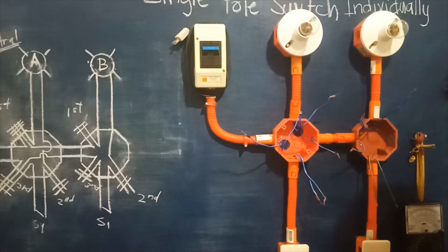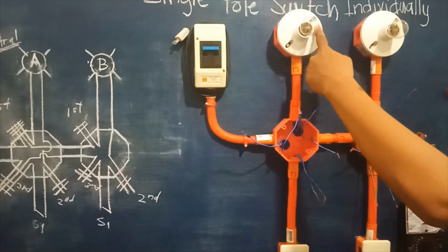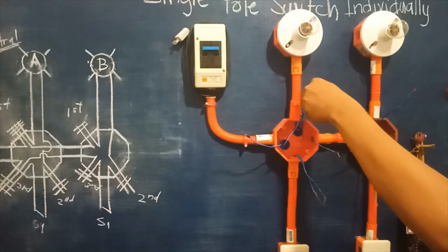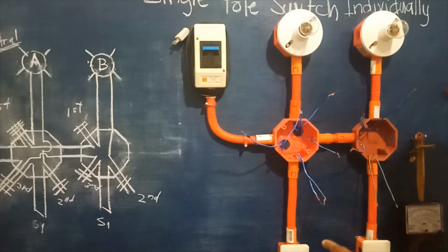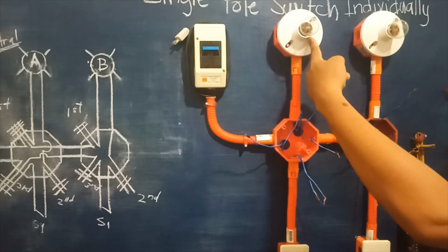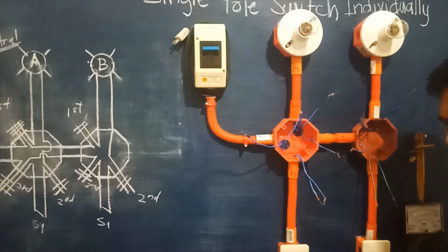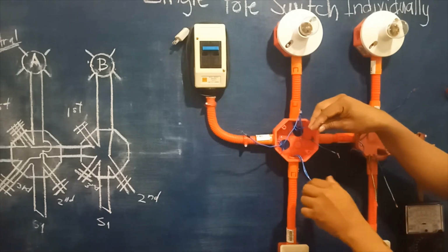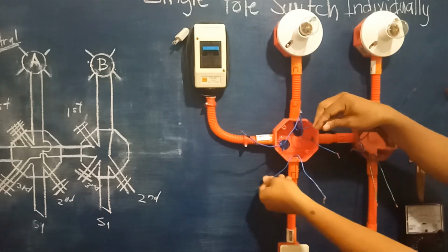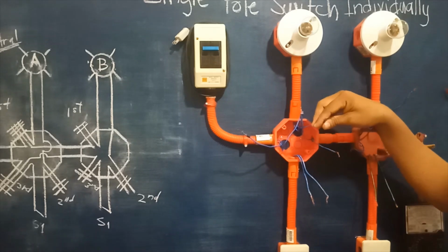Now in the second cycle connections, of course, from the load, this wire is to be connected to the control device as to where it is being controlled. So in our case, bulb A to be controlled in the first location of the switch using the single pole switch. So this one to be controlled right here. You can actually interchange the wire already coming from the control device.